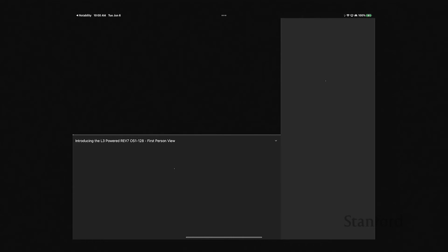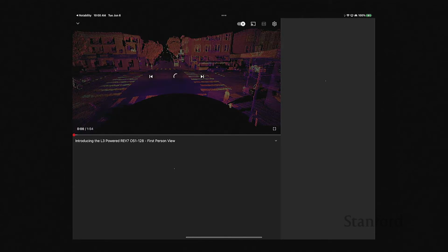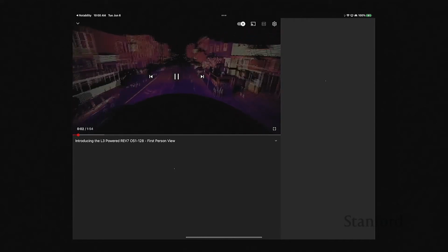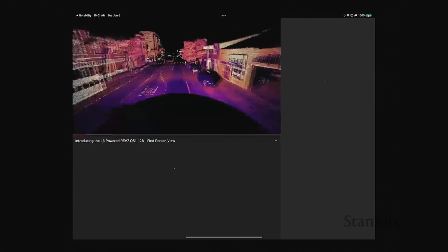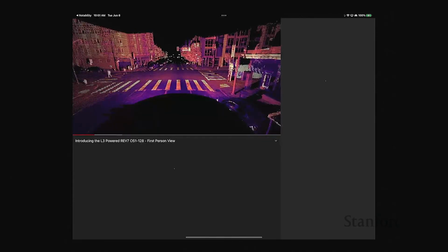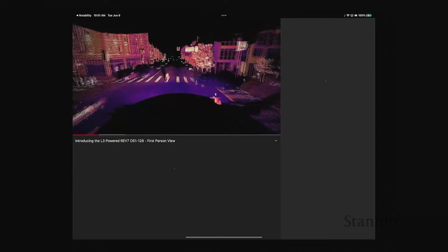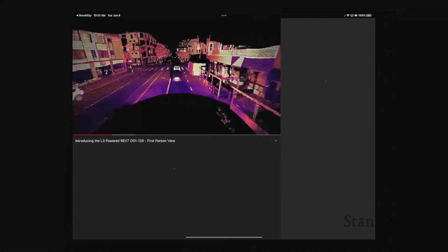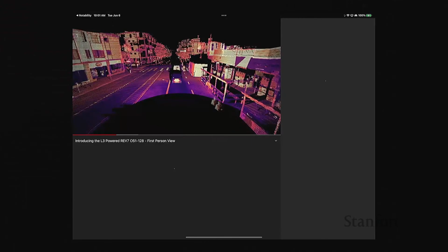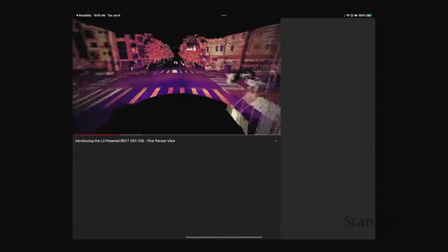This is a direct detection LiDAR we are going to look at. And this is just a point cloud. It's mounted on a car driving around. For some reason, it's not going to full resolution. But here you see, they're showing just one frame. So it's at 10 frames a second, I think. And it's not overlaying multiple frames or doing SLAM or anything like that. As you can see, things that are moving around have almost no motion blur.